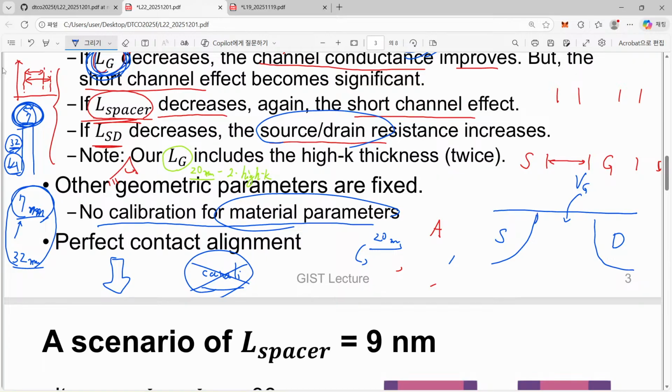So electrons are injected into this channel region. After that, it is accelerated. Why is it accelerated? Only because we have applied a higher VD than the source value. Since it is negatively charged, it is accelerated or drawn to the highly biased region.